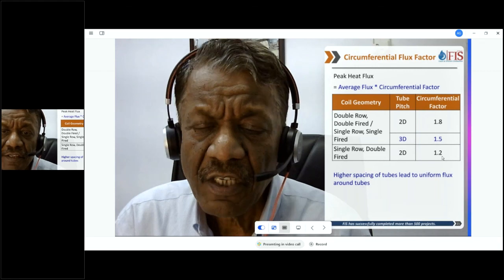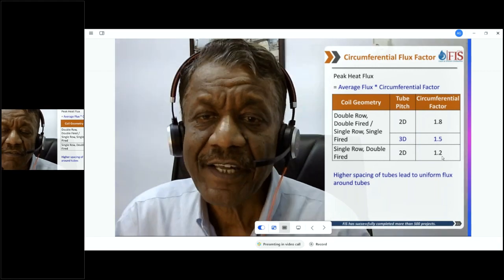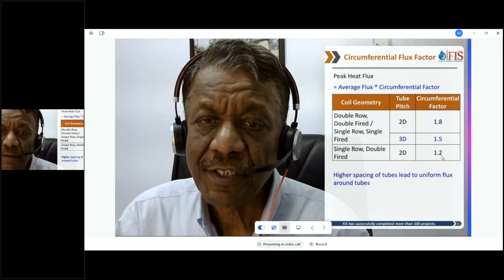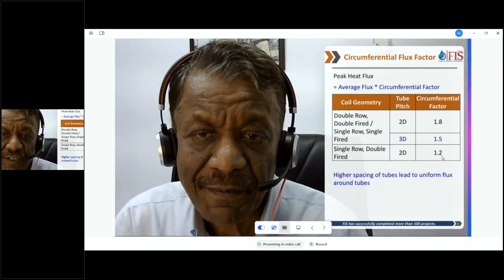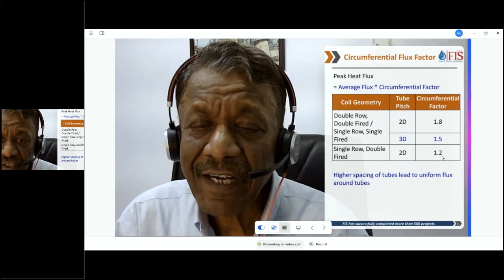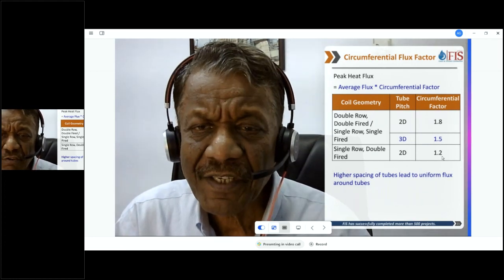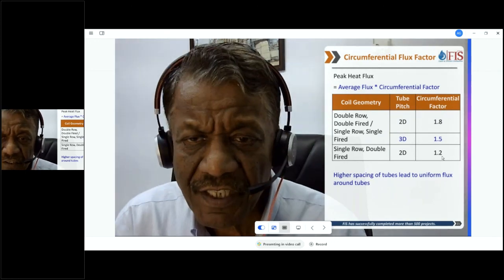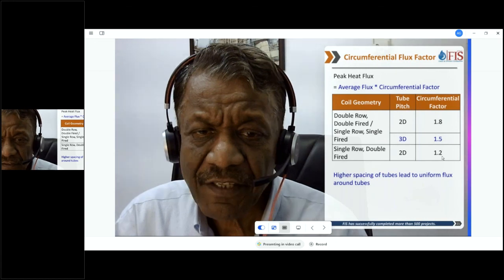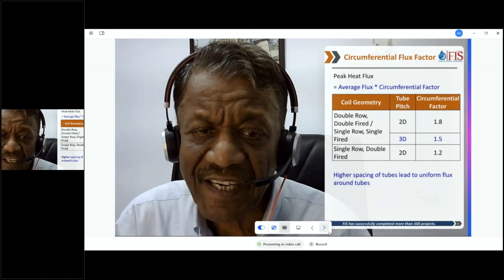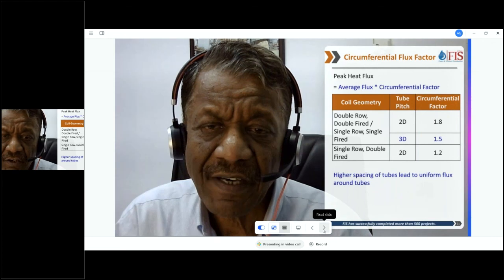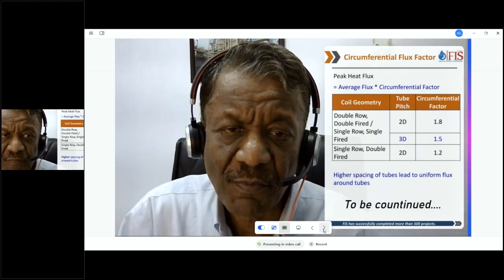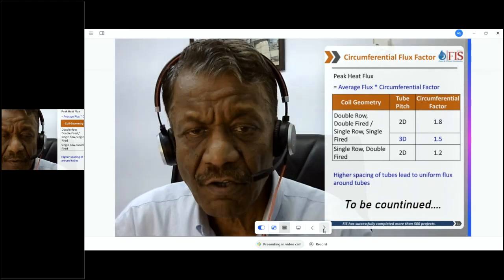So you can see we can do double firing and bring down the maximum. Now, what is the significance of maximum flux? Maximum flux defines the maximum film temperature and maximum tube metal temperature, it defines the metallurgy, so it basically controls a number of parameters. When we're designing, the users or the licensors will specify that they don't want the flux to be more than 1.8 or 1.5,